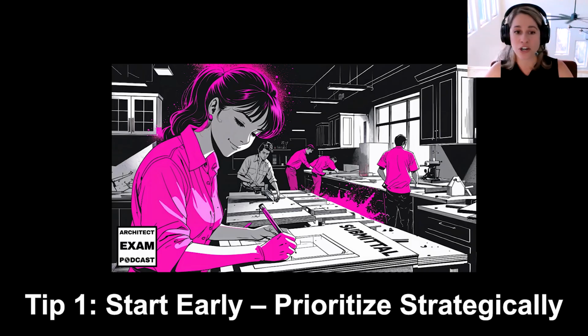So first, start early, prioritize your plan, and be very strategic about it. So create that comprehensive submittal schedule first. This is at project kickoff, identifying all required submittals and when they should be submitted. So a date associated with every submittal.